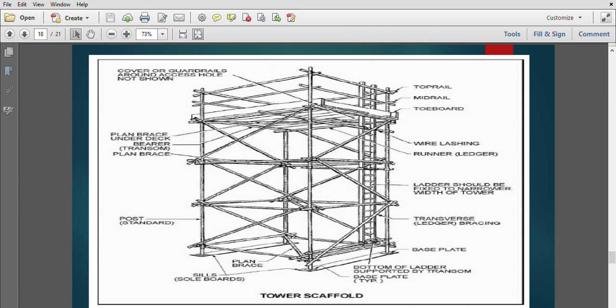So your bracing, sometimes in the Aramco exam, the placement of bracing is very far from the node point. Sometimes 600 mm from here to here. So it should be within 300 mm. So from here to top 300, from here to here 300. Less is okay, more is problem.